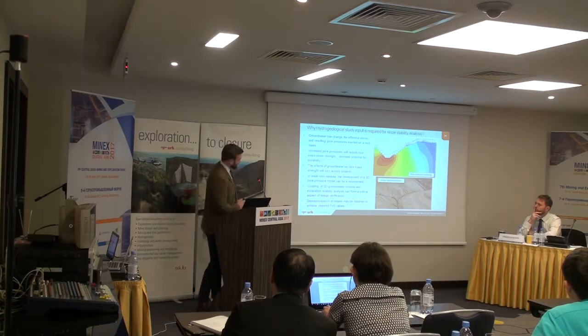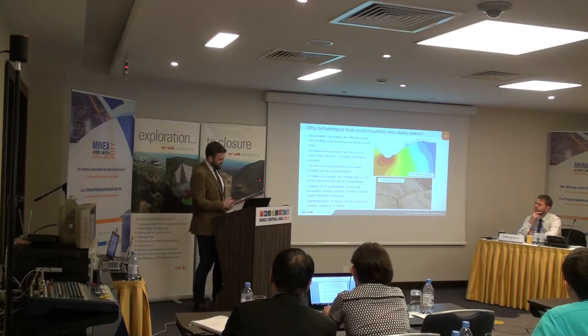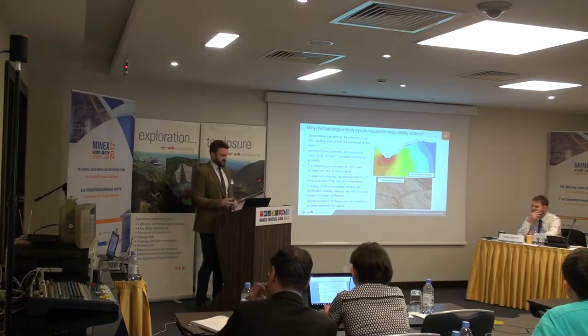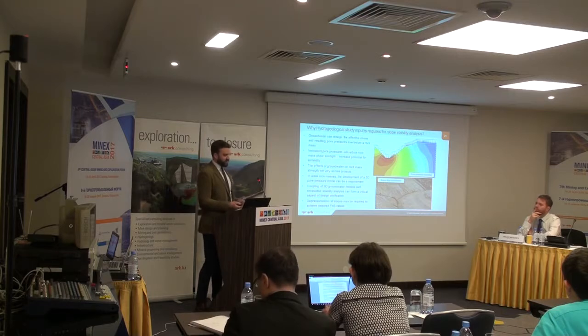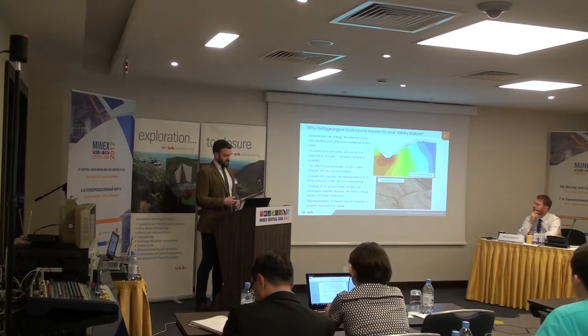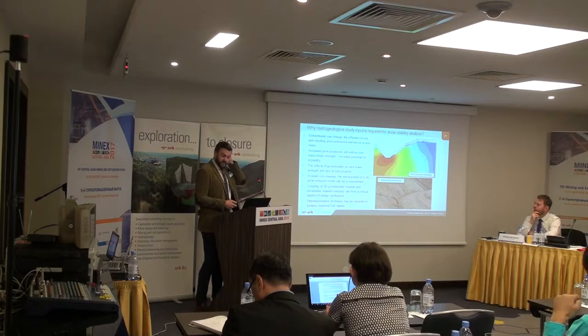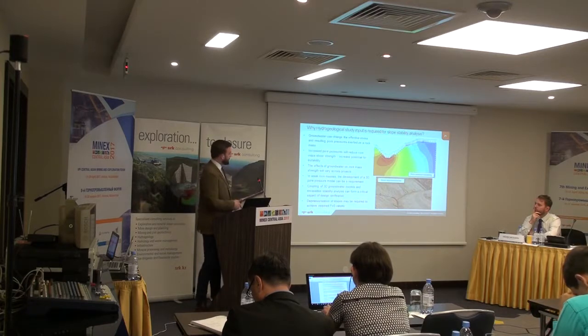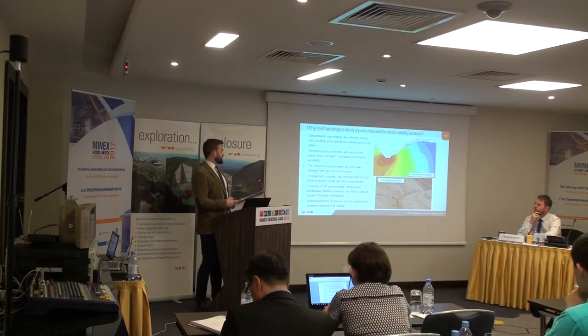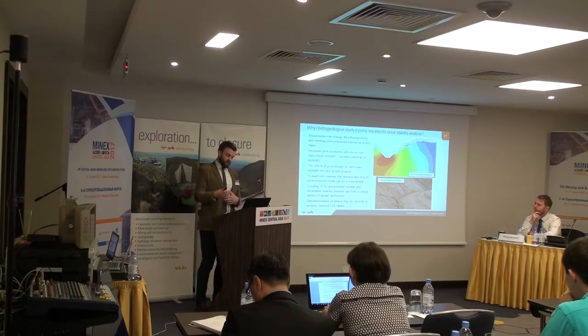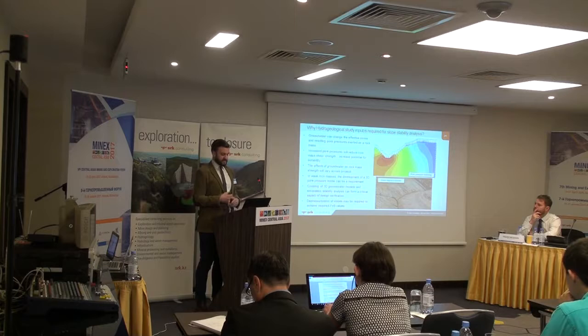I'm running out of time here, so I'm just going to flick through these next slides. So as I said, the groundwater can change the effective stress and result in pore pressure exerted on the rock mass. And any increased pore pressure reduces rock mass shear strength and increases potential for instability. And the effects of the groundwater on rock mass strength will vary across projects, and we really need to understand the impacts and what's critical to the pit slope design, especially in weaker rock masses.